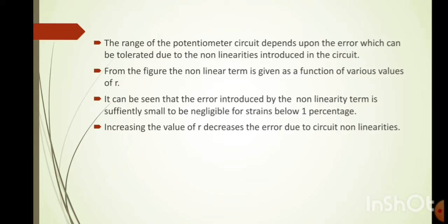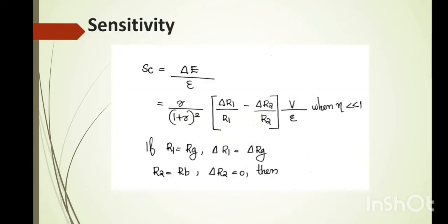It can be seen that the error introduced by the non-linearity term is sufficiently small to be negligible for strains below 1%. Increasing the value of R decreases the error due to circuit non-linearity.